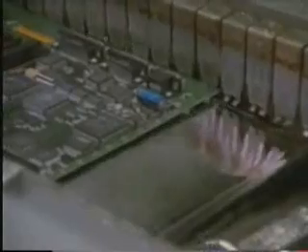Bubbly solder preheats the boards before they encounter hot flowing solder. This secures all the leads and any components attached to the bottom of the board. It also fills any vias or other exposed holes in the circuit board. From beneath, we see the hot solder just touches the wire leads.